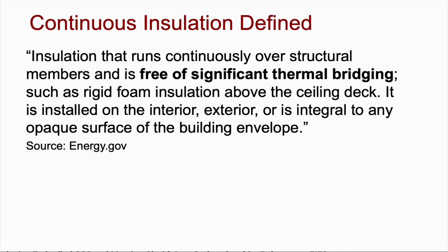Continuous insulation defined. Continuous insulation is insulation that runs continuously over structural members and is free of significant thermal bridging, such as rigid foam insulation above the ceiling deck. It is installed on the interior, exterior, or is integral to any opaque surface of the building envelope.